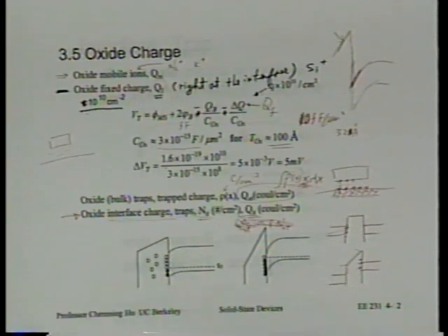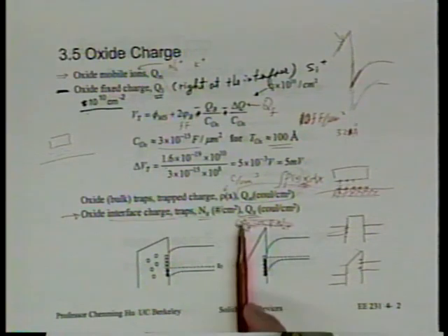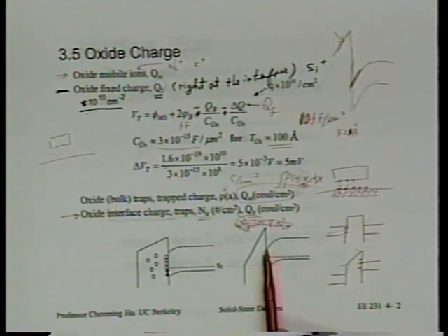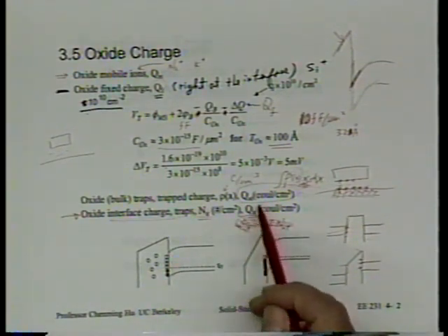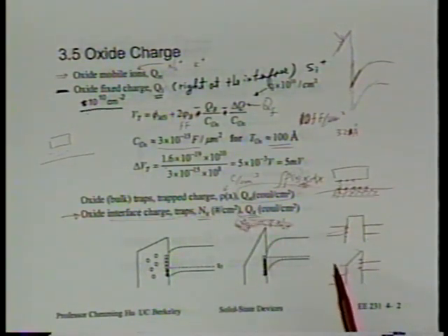Okay? That certainly has a lot of impact, including, when we're applying Vg, we thought that voltage will give us a change of Q inversion, therefore changing current. It may not, because some of that may be taken up by this NIT, QIT, right? Possible, okay? So including that. That's not one of the most severe concerns. Turns out the biggest concern is this QIT also can reduce our mobility, all right? But there are several subtle things about this interface trap that put it in a separate class of the traps or charge in the MOS system.